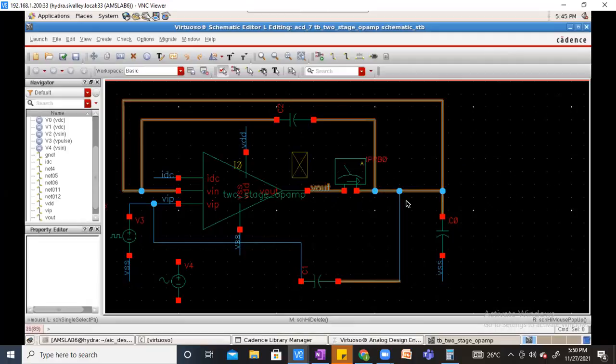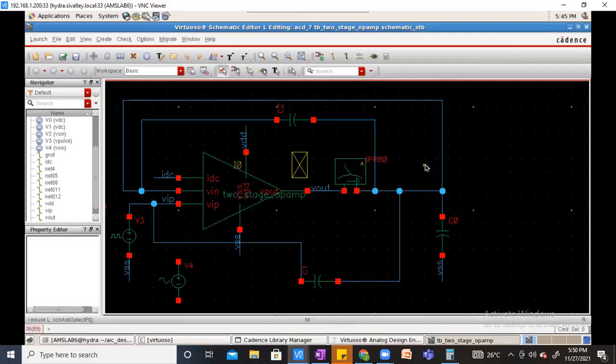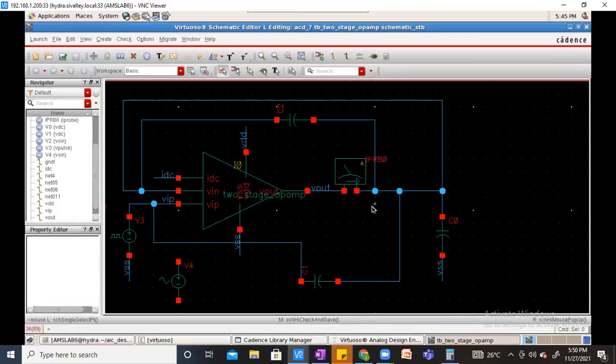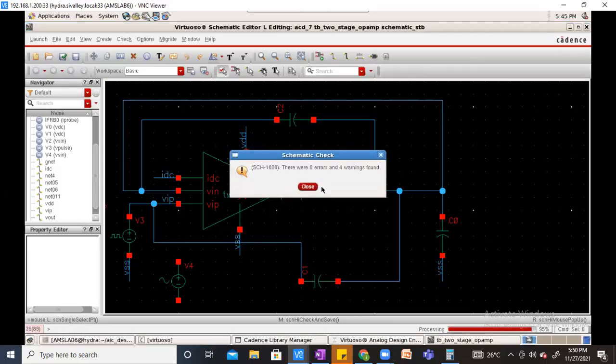So this loop got broken, this also and this also. This is how we should identify it in any complex circuit to do the stability analysis. So now I have placed it at the immediate output of the op-amp so that it will break all the loops. Definitely the loop will start at the output point only, right? No matter whether it goes to which input or where it's going, I don't mind. But it definitely should start at the output node itself. So if I break the output node, then it will break all the loops. Simple. Now let's do the stability analysis here.